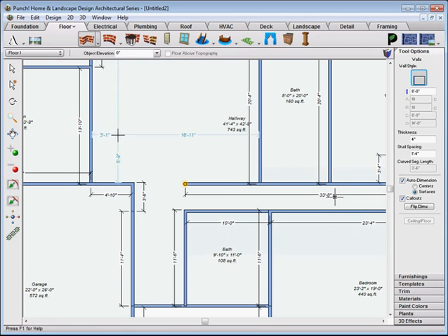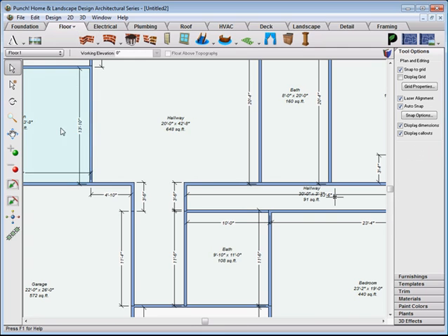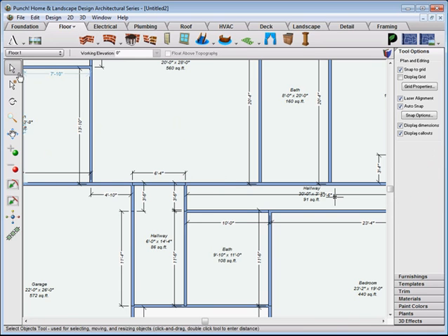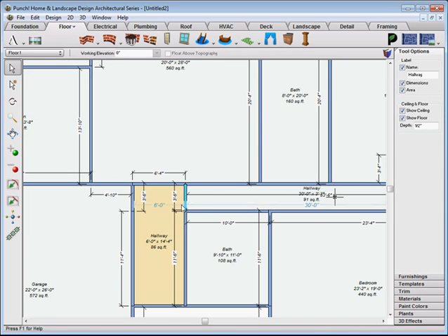Cased openings can be used as doorways between spaces while leaving the rooms separated as individual rooms. We'll connect these walls back up, and you'll see as I work, the rooms become divided again. And we'll add one more wall back to divide off the living room from that hallway. And you'll see now that each is its own room again. Now each can have its own floor material, and each will have its own estimate.